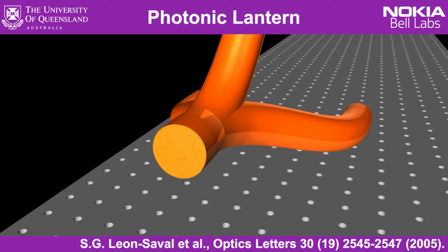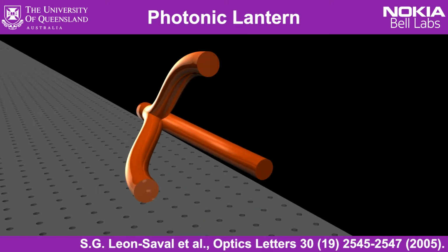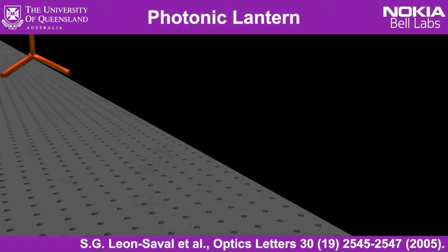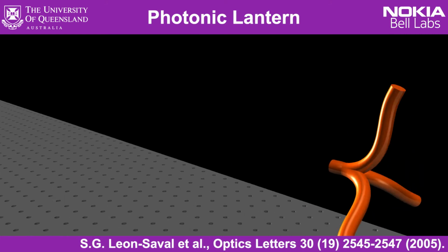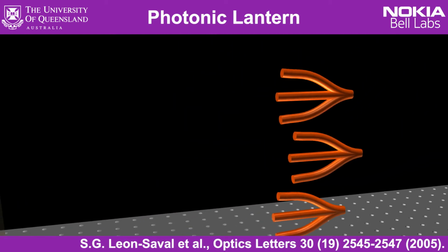It's a tapering of an n-mode multi-mode fiber on one end into n single-mode fibers on the other end. So it's a full three-dimensional refractive index profile. It's a lossless device whereby a spatial mode put into one end gets split up and decomposed into its individual spatial components as diffraction-limited spots on the other end. The photonic lantern was originally invented for astronomy, where light is collected by the telescopes into a multi-mode fiber before being sent to single-mode spectrometers.